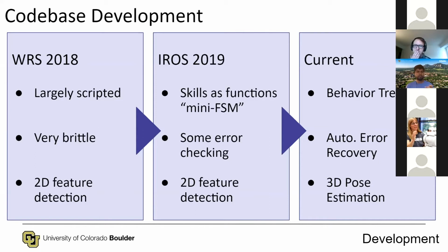Hence, to reduce this amount of repeated code, we wrapped common actions into skill functions. This looks straightforward at first, but with different failures, we added more and more condition checks and phases to our skills. At competition time, we saw that our skill functions looked like a hacked-together piece of finite state machine. We found that behavior trees are a favorable alternative to these informal FSMs.